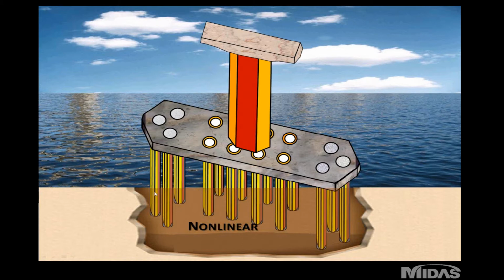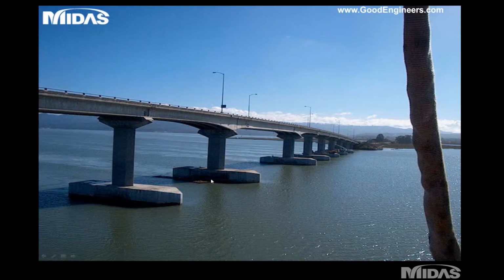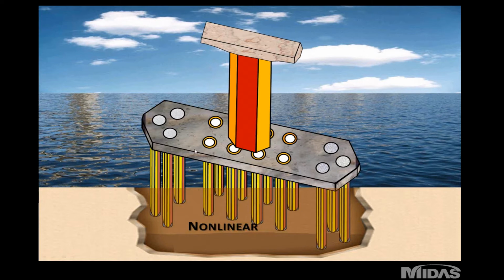The piles are about 40 feet into the ground, and they're about 50 feet cantilever above the mud line, all the way to the water surface, which you can see here. So these piles are almost like a cantilever sitting on pile caps, and the pile cap is above the water surface.